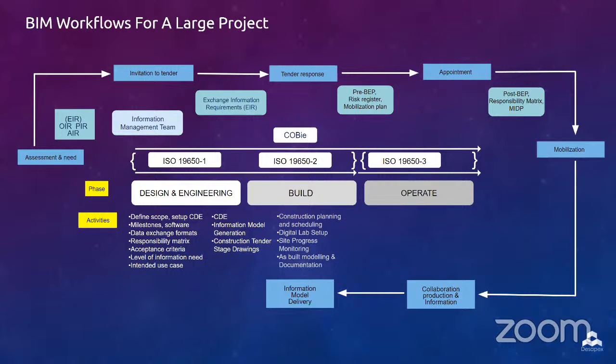With the help of routine coordination meetings, implementation, proper review process, and construction progress monitoring, and also the accurate as-built model updation using scanned data, the construction phase can be completed with minimal waste of materials and time and cost overrun. After the construction, the contractor needs to submit the as-built BIM model, which is enriched with the level of information need, which is defined prior in the BEP and in the EIR, with all the relevant other data of the COBie and facility management, also including the technical specifications, all embedded into the BIM model,